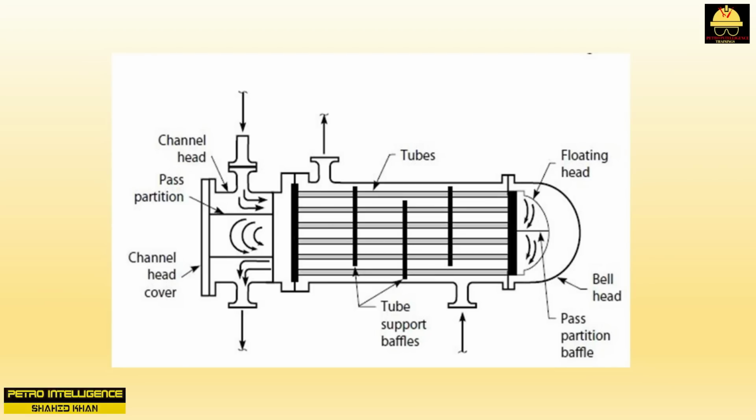On the other hand, cleaning the shell side requires pulling the entire bundle out of the shell. This is a massive undertaking requiring a special bundle pulling machine and a large crew of pipe fitters. Then comes the hard part, cleaning the bundle. If the deposits are soluble in a solvent, the shell may be soaked in a chemical bath. Sometimes this bath must be kept hot to dissolve the deposits at a reasonable rate. Sometimes the deposits must be attacked with a hydroblast machine. If the design engineer has selected a correct tube pitch, cleaning the shell side of an exchanger with a hydroblast machine may be a reasonable proposition.